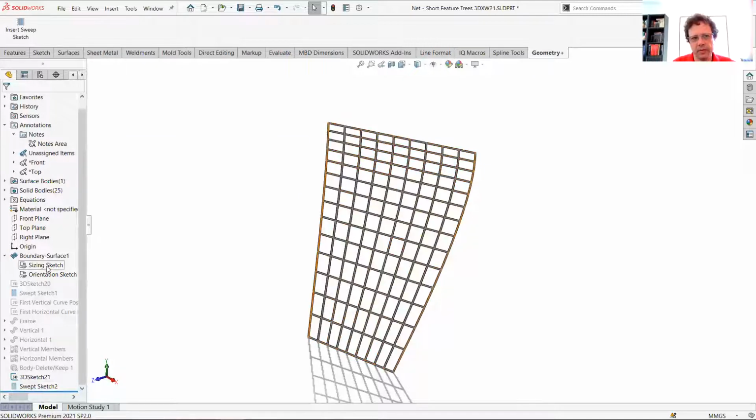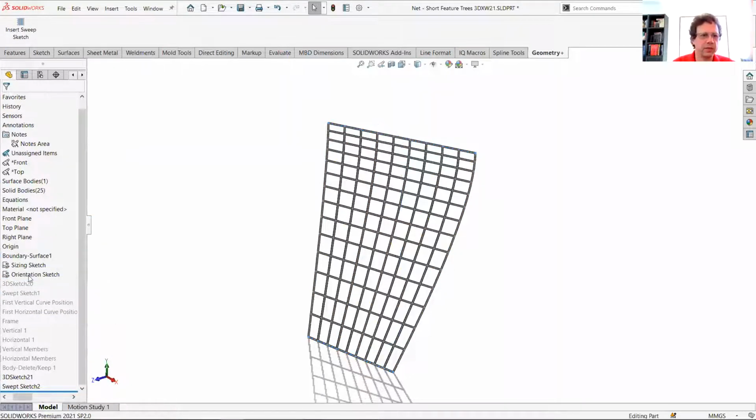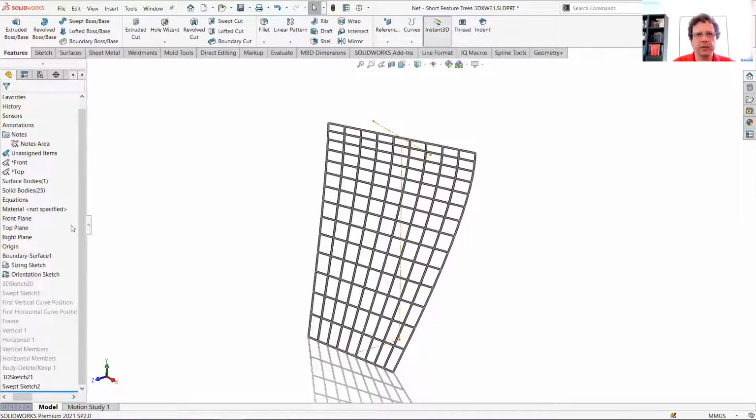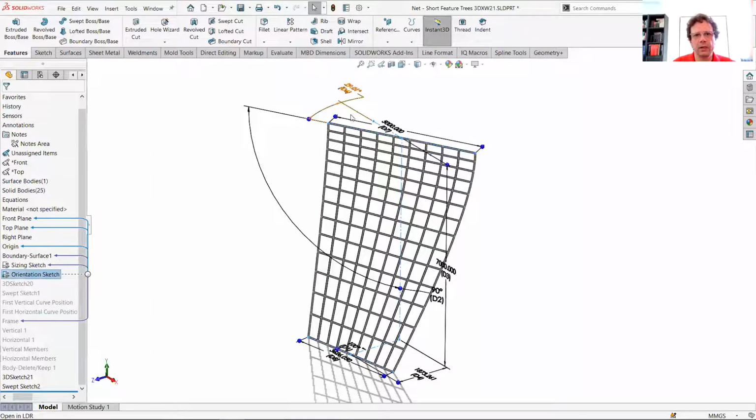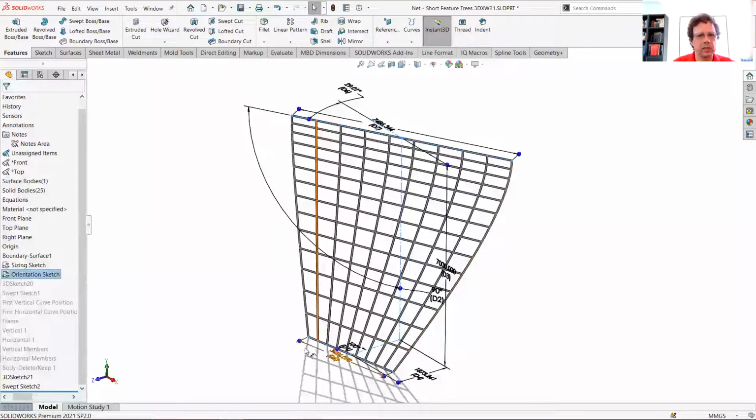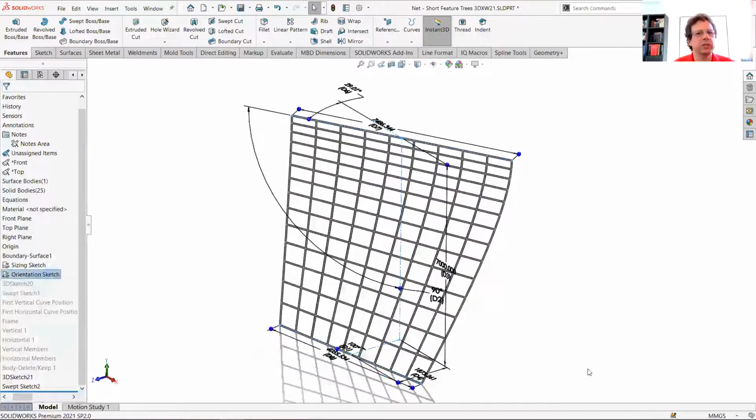So that tells me that has a couple of properties. Number one, if I change the orientation sketch, right? So let's try to do that. Let's make this visible. Maybe turning on Instant 3D, clicking on this and do something crazy. I don't know, let's make this bigger. It worked. Obviously it works because face curves are smart enough to maintain their position.